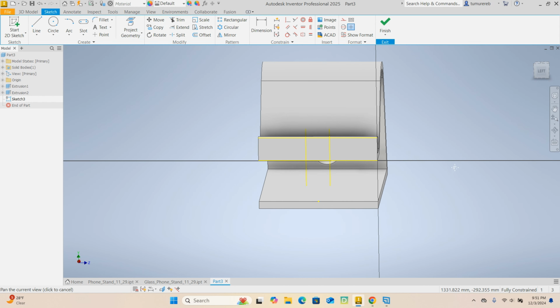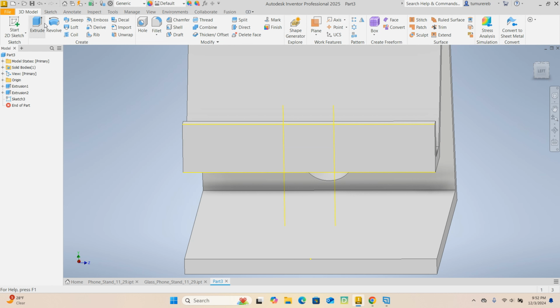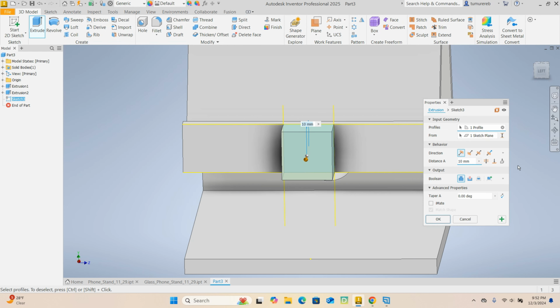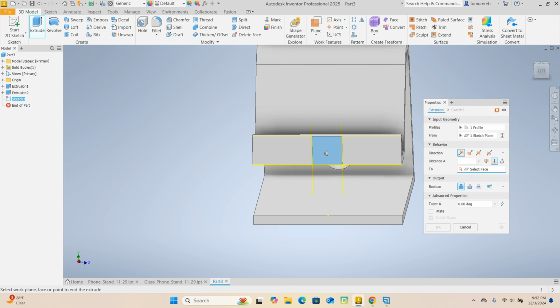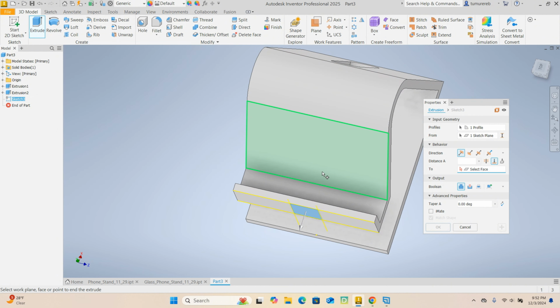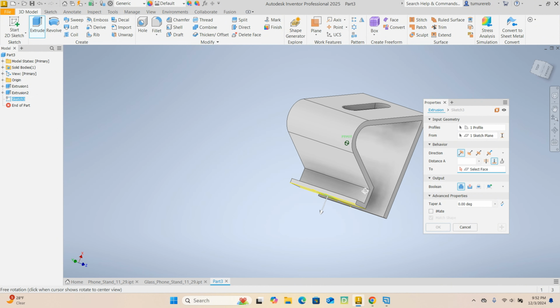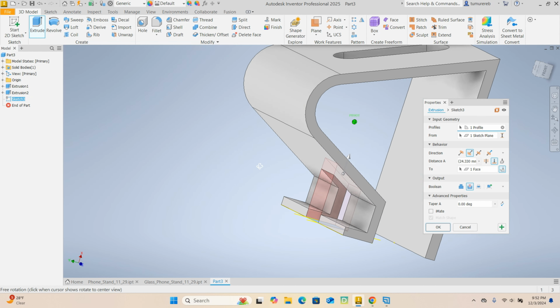So you have a square now. Okay, finish sketch. Extrude. Let's go back to extrude to again. So that's this option, and don't type in a distance. Then I want you to shift and middle button select it. See the face you want to extrude to. I'm going to select here inside. I'm going to go all the way to here. Why not?